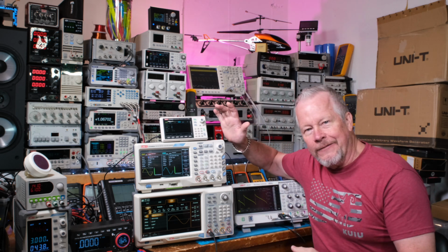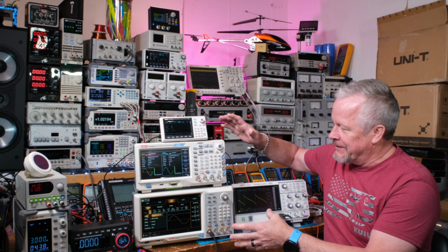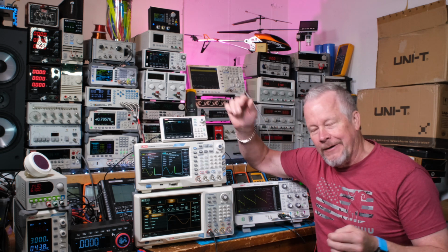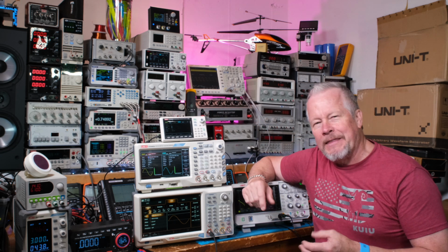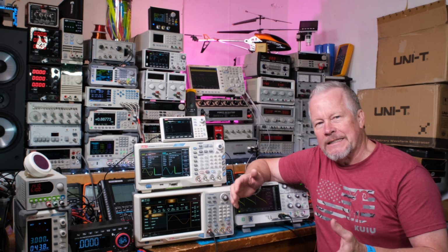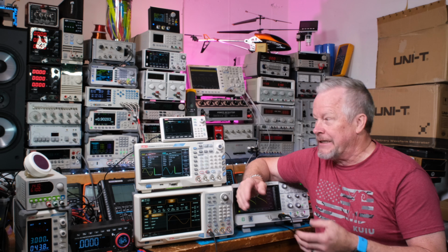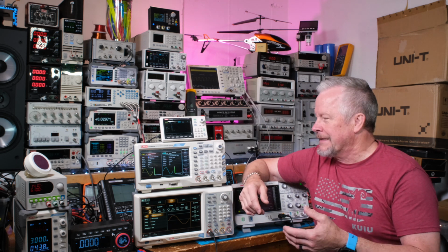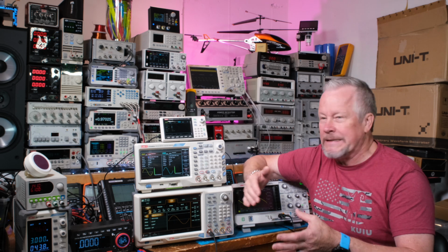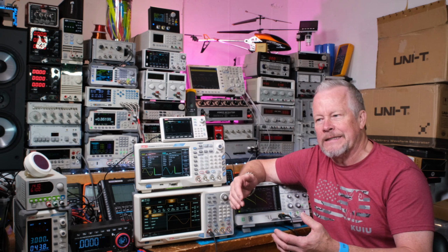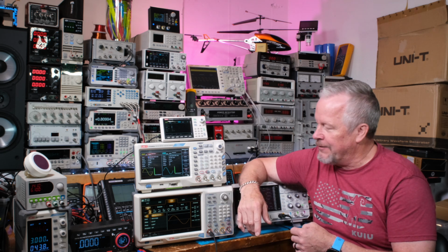There's an accuracy thing, right? So you'd imagine the accuracy of, say, this beast is better than this little guy. And you'd be right. So there's a thing called parts per million, right? Especially with oscillators and things that count on oscillators, like generators, they have 10 megahertz sync inputs. So things on your bench might all be synced up to this clock so that your counters and all your electronics are all synced up, okay? If you're into heavy digital or communications type stuff.